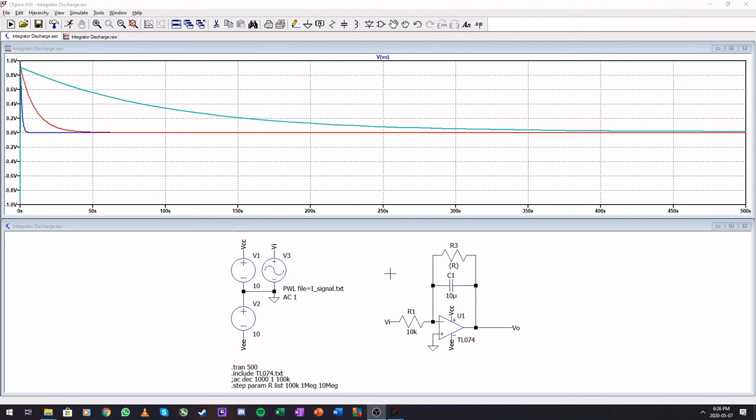If you're not keeping it for a very long time, you can use smaller resistors, and that is typically how you do averaging. So from the DC problem where we did the extraction, you want that value to be a bit more dynamic. So the 2.2 kilo ohm that was used for integration to just get the DC out is a perfect fit. So the moment that the DC falls away, the output signal will also go to 0.